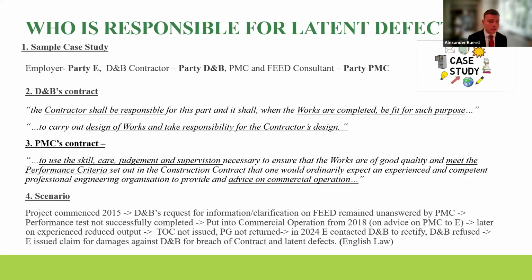And under English law, there is a 6-year limitation on construction contract claims. Sorry, if the contract was signed as a deed, that would go up to 12 years. And so it's quite common that you see construction contracts for certain works and various guarantees in deed form, so it gives an employer a bit more protection.